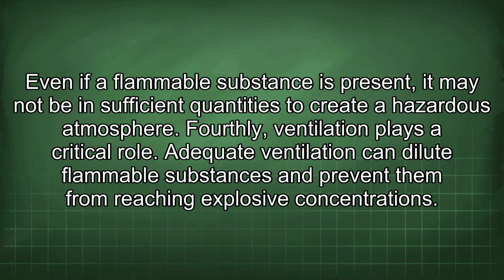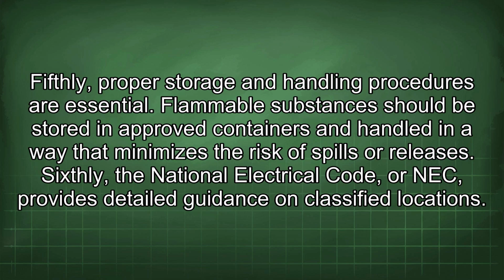Fourthly, ventilation plays a critical role. Adequate ventilation can dilute flammable substances and prevent them from reaching explosive concentrations. Fifthly, proper storage and handling procedures are essential. Flammable substances should be stored in approved containers and handled in a way that minimizes the risk of spills or releases. Sixthly, the National Electrical Code, or NEC, provides detailed guidance on classified locations.